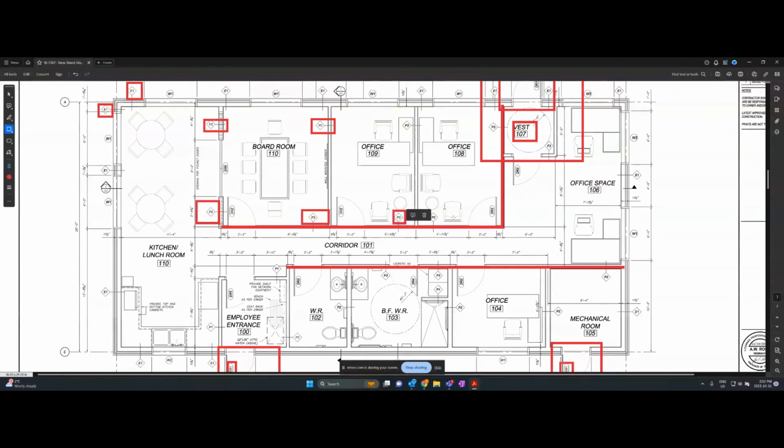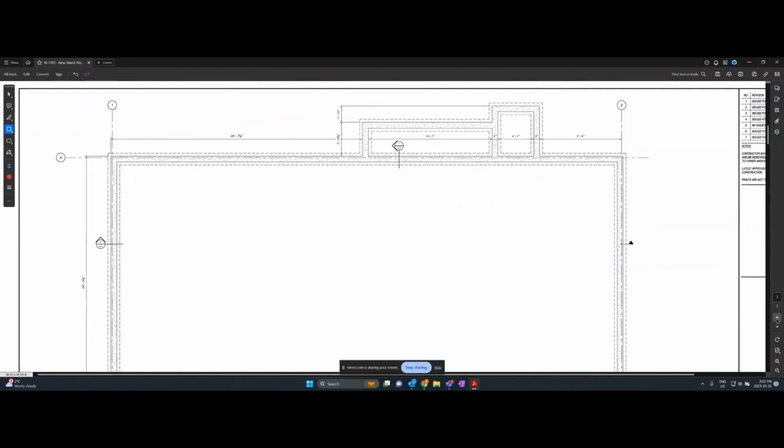So basically these little diamonds tell you exactly what that wall's made of. So you have to basically look at this drawing, go back to drawing A0, and then you know how to build your walls. So as you'll see here, too, we have a door. Again, we have the door numbers, okay? And then we have the room names and room numbers, which will all correspond with the other drawings that we have seen already.